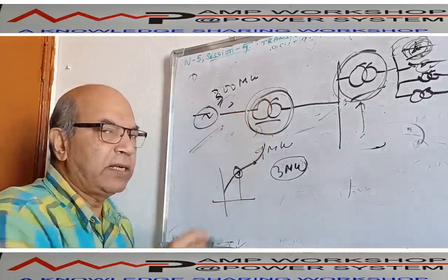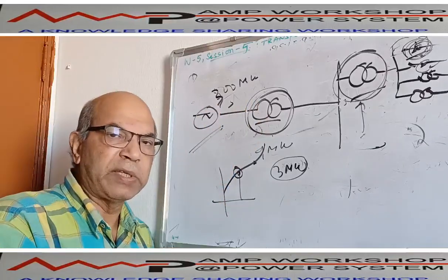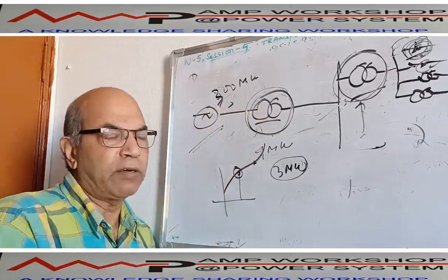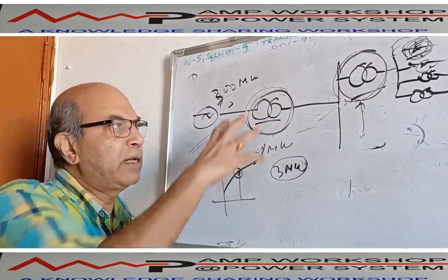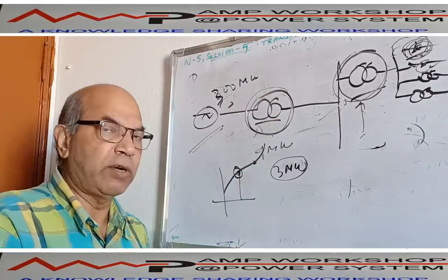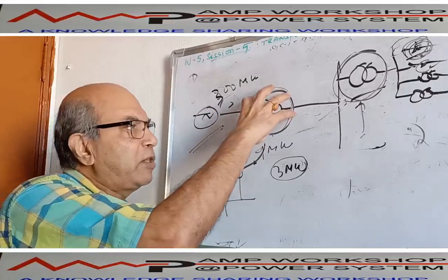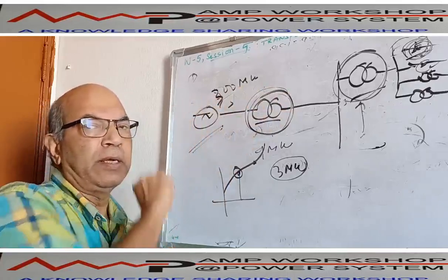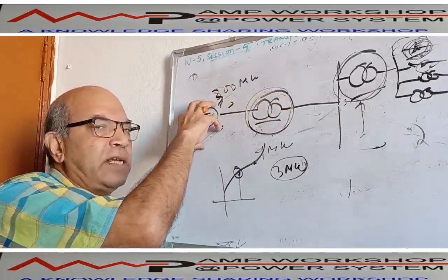In this case, for the generating transformer, we generally do not need to put any spare capacity, but if somebody wants to, you can put 5% or 10% spare capacity, because this is a huge size of generator transformer. Normally, for this type of transformer, spare capacity is not mandatory. So normally 5 to 10% spare capacity, and this capacity will be decided based on the generator capacity.